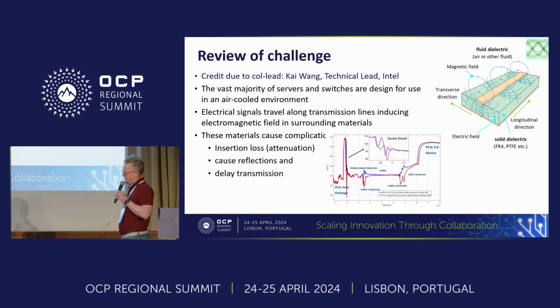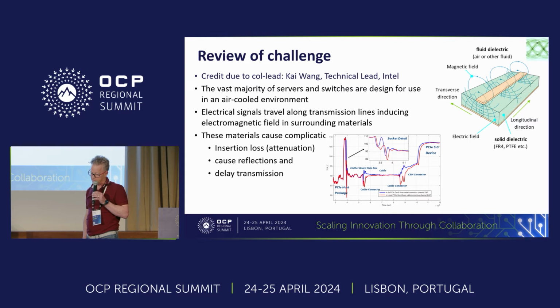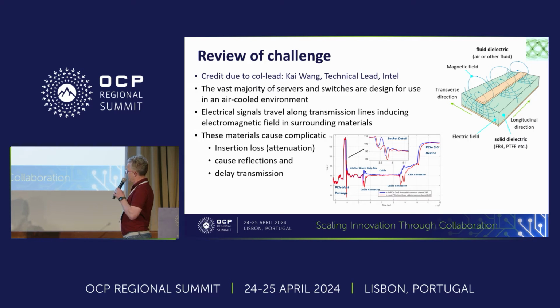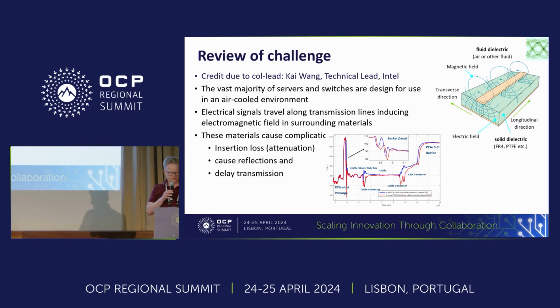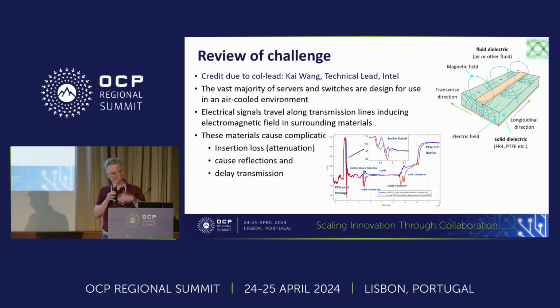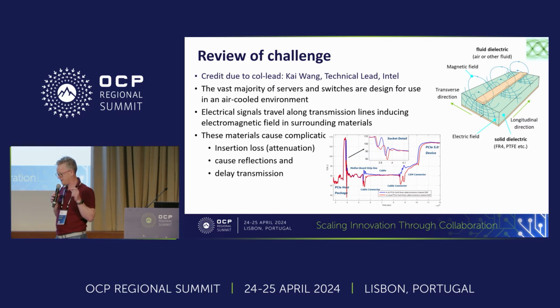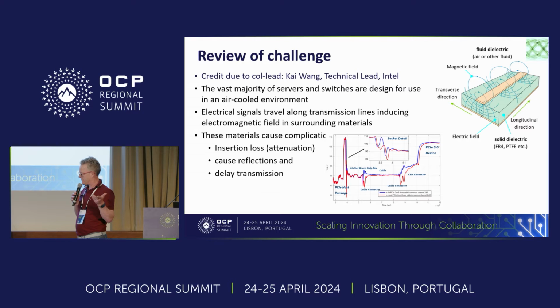And in the image, you can see along the horizontal axis a time trace of information passing along a transmission line that has multiple components, and you can discern the change in the impedance, the resistance to the transmission of that information, as the signal passes in between different types of equipment that are in air, in blue, and immersed in liquid, in red. Some of them have a small change, and some of them have a large impact. And it's the large impact items that are going to spoil the party for immersion. Strangely enough, sometimes you get a reduction in impedance that sounds like it's an improvement in performance, but any change to the signal causes things to go out of skew in the timing of the reception of the information. So it's not a case of it's faster in immersion, which may be the case, but just because it's different, it means you've got to retime, and that's where the problem comes from.